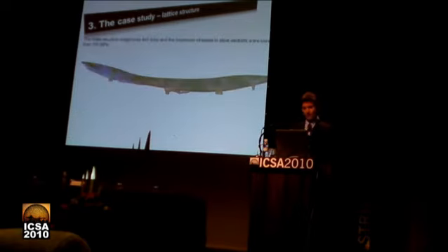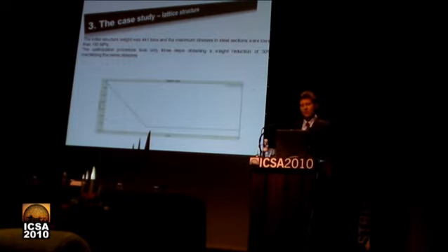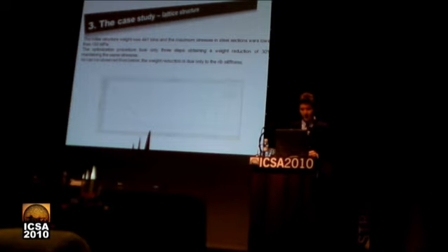So in the first step the structure weighed 441 tons, and the maximum stress in the steel sections was lower than 150 megapascal. The size optimization procedure reduces the weight by about 30%, maintaining the same stress. As you can see in the picture, only one of the three components, in particular the rib, has its section reduced. The other two components remain the same. So this variation represents that the stress remains in the same sections.